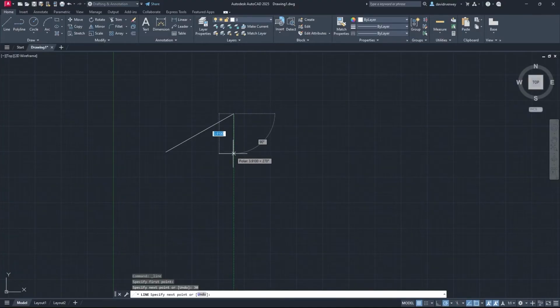One thing to note is when you are doing angles, AutoCAD will take into account what you have as a preset for that. So it's always preset to start on the bottom right, I believe, and that's what I have here. So what you can see here is when I click Enter, my line is then created. I can also just draw down, and I can click down, and then I can click on to the left, and I have a perfect triangle.